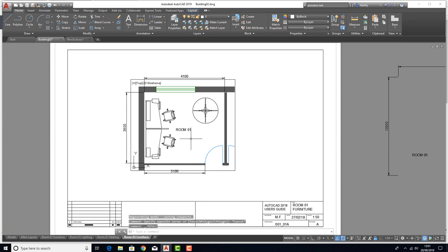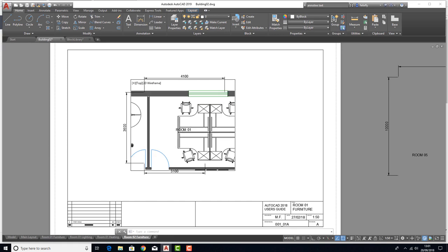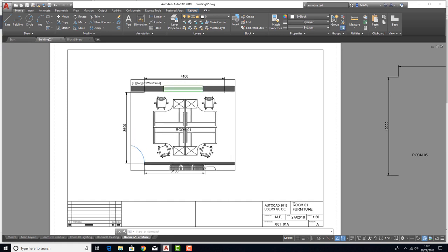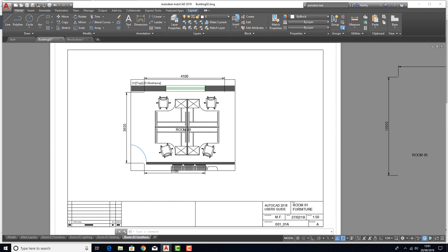So we can click in our viewport. We'll need to unlock it for this, and once we've unlocked it, we hold down our middle mouse button, but before we move it, after we've held down the middle mouse button, we hold down shift. Now what shift will do, if I show you without shift, hold down our mouse button, we're going to pan this to get room 2, but look, we're going up a bit, we're going down a bit. How do we know we're going to still be in line and we're not going to throw everything off?